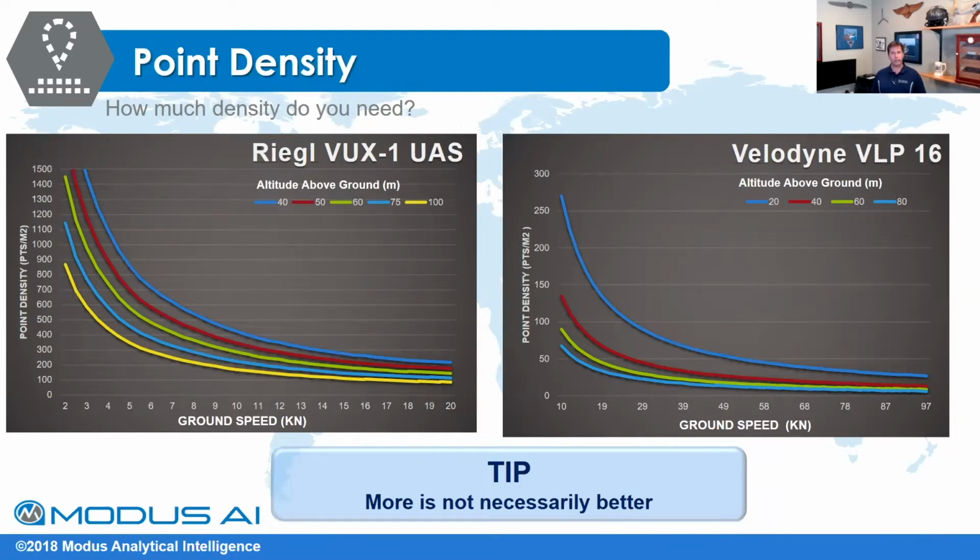So again, knowing those data standards are really, really important, and we'll go over a little bit more of that in detail. But the biggest thing is not to over collect, because if you over collect, then you're going to spend a lot more money in labor costs and processing cost on the backside, down sampling your data sets and tiling them into smaller chunks, which with drone data, since you're covering small areas, you shouldn't have to. But if you're going to be collecting such large volumes like this, you'll run into those schemes that you typically see in aerial type collections or projects.